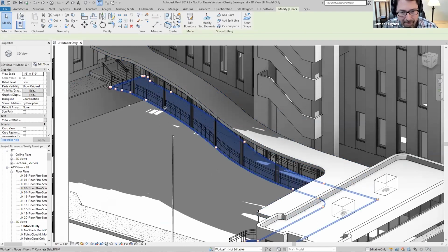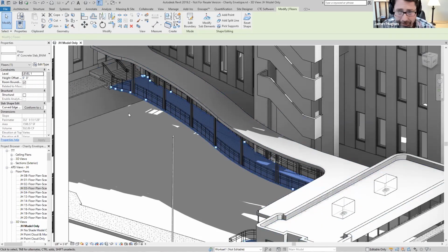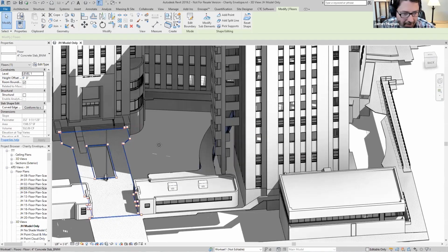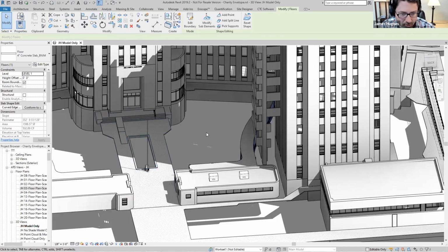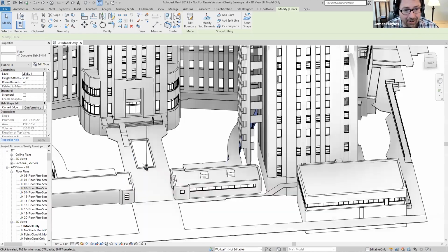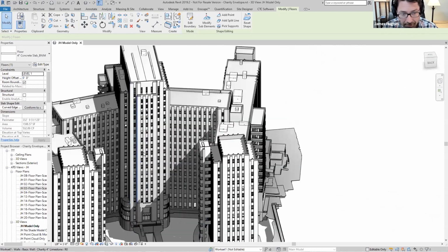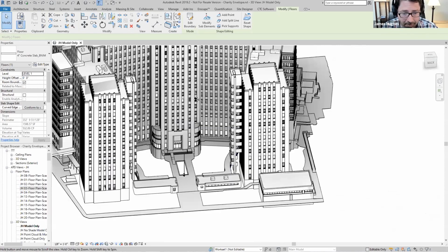But if you were going to measure this piece, it would be extremely difficult to pull that off in field, even given 2 hours. In all total, we set up 4 scans in this courtyard. So it went left, center, right, and then back here. And those were 3-minute scans. So inside of 20 minutes, even with setup, we were done. And it had shined all the way up 20 stories. It fired inside of windows that would later corroborate some of those interior scans that were linked to it.